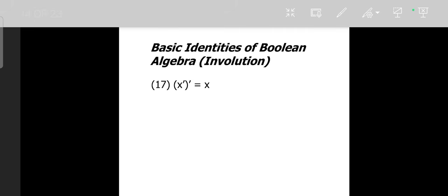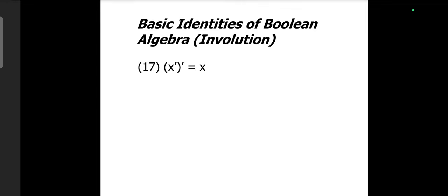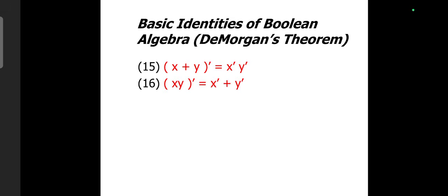In the last class, we discussed De Morgan's theorem. The concept we just learned can be extended to expressions involving multiple variables also. We have seen it for two variables. They are particularly important when designing circuits using NAND gates and NOR gates, which are considered universal gates. These theorems are extensively used in logic circuit implementation because they allow designers to convert circuits into equivalent forms using different gate combinations.